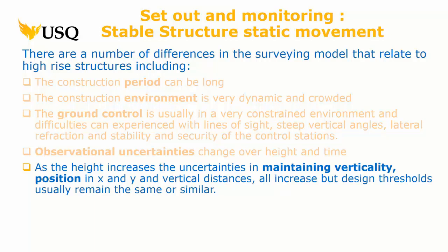So on floor 28 or 56, they're going to say the pillars on the four corners, or the steel work, have to be set out to a certain precision, a tolerance, which will be the same as the first floor. But getting further away, your tolerance or your precision, standard deviation or whatever, is going to change because of the distance you are away from your control.